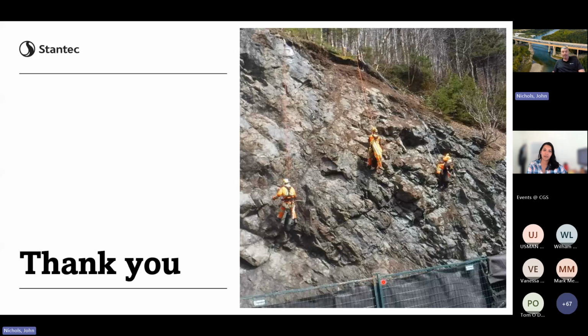Yeah. So tension rock anchors, or active anchors, typically we use those if we know we have a defined structure or a defined discontinuity, and we think there's value in pulling that discontinuity closer together.